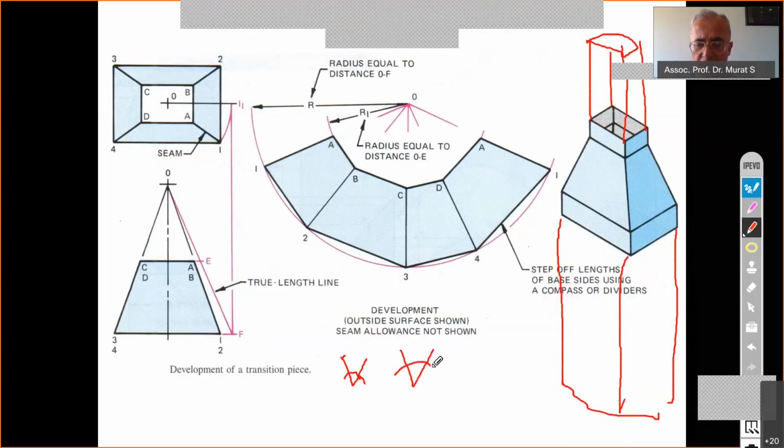It looks like a capital V with such a curly arc, and then put a dot. It is to say volumetric flow rate. How can it be calculated? Multiplying the cross-sectional area with the average speed of the flow. Within the channel, we have, for instance, conditioned air flow. Air is flowing and has a certain average flow velocity. If you multiply flow velocity with the cross-sectional area, we obtain the volumetric flow rate. The unit of this in the SI unit system is cubic meter per second.